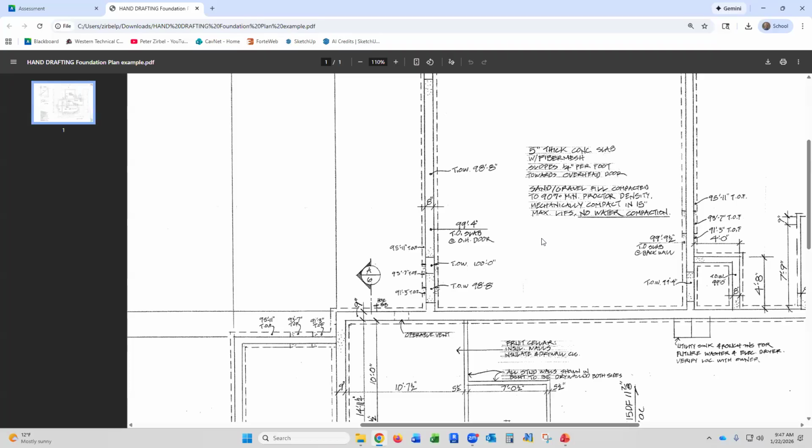That footing steps. Now, I told you before that you can keep the bottom at a sloped angle, but what you're really interested in, for the people that are laying out the concrete wall, they need to know where that wall steps up to go from the lower basement level to the higher garage slab level. And that's what's showing here. So this is my foundation wall, and I've got my top of wall with a little notch for a person door. And then it goes back up, and then I've got another top of wall for the garage door.